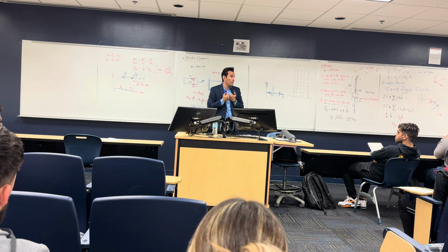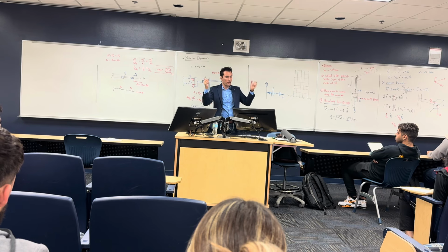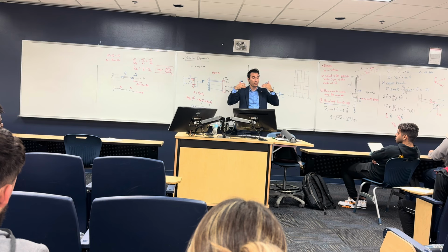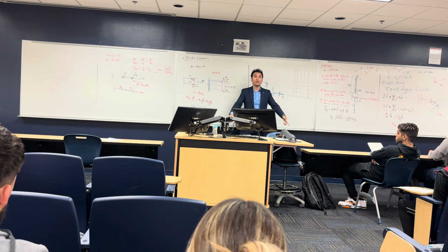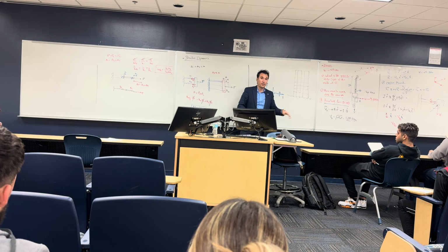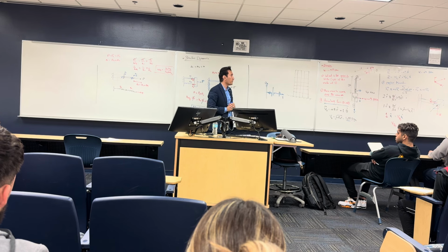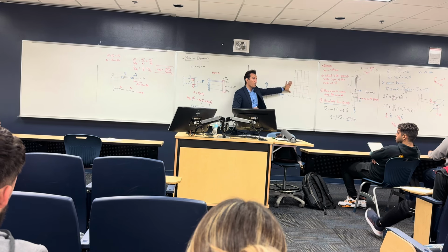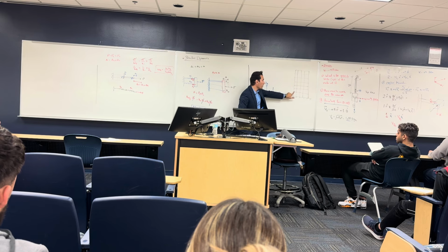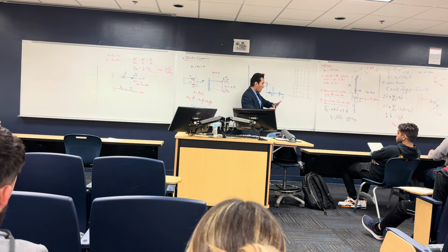When I get something from the architect, I need to design the superstructure first, design the columns, design the beams, design the slabs. Okay? Once I do this, I find the loads on the foundation and then design the foundation. Either it's going to be isolated, piles, raft, foundation, whatever it is. But here, looking at this structure, I'm looking at columns, beams, and slabs. That's how the structure looks to me.